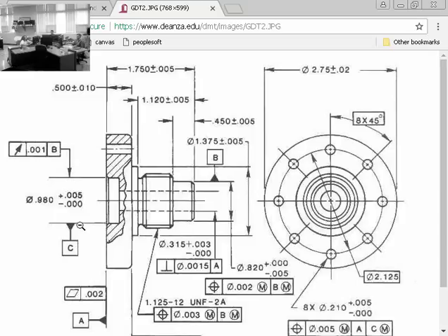So you look at this one and you might be thinking, oh, okay, they are establishing this wall right here as datum reference C. And that makes sense to think that way. But there's a tricky rule when dealing with cylinders. Since they have attached this C to the dimension of this cylinder opening, they're actually establishing the cylinder itself as being a datum. So technically they are establishing the center line of this hole as the datum.